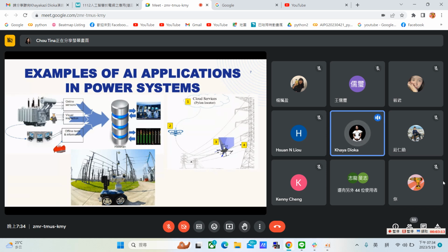You get all that information, and then you are sending it back to the system operator, to the engineer to say, we've got severe weather conditions. Maybe this line should be switched out because it is our main corridor, but if we were to lose it in service, we're going to have more problems.